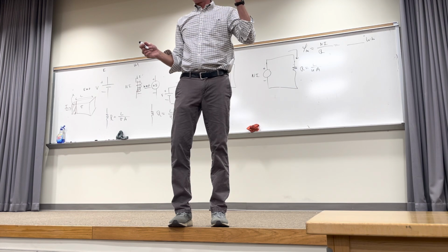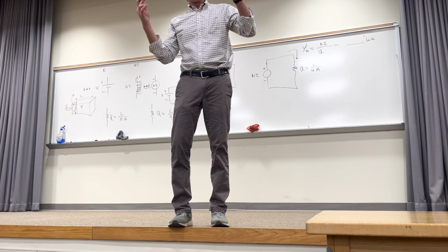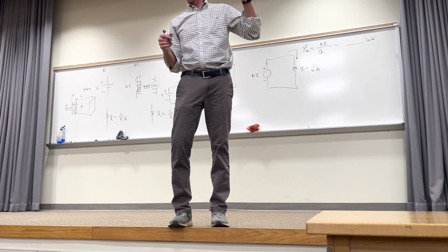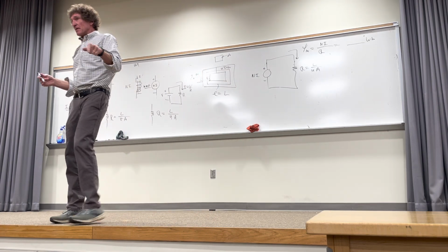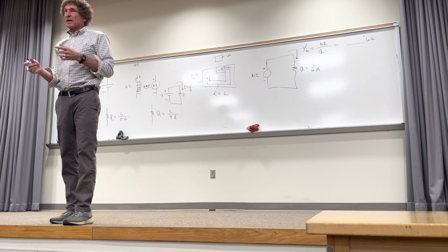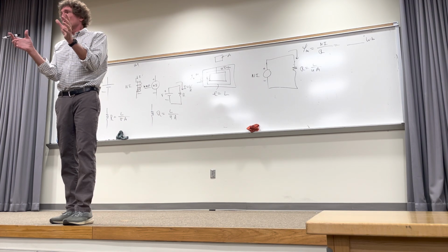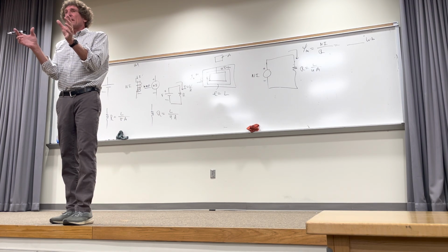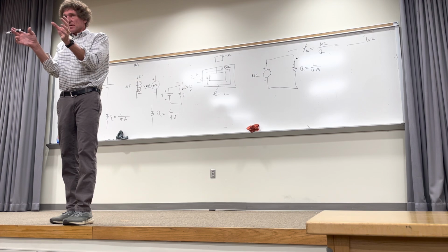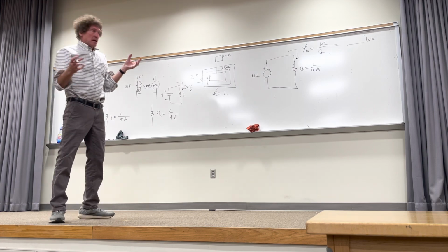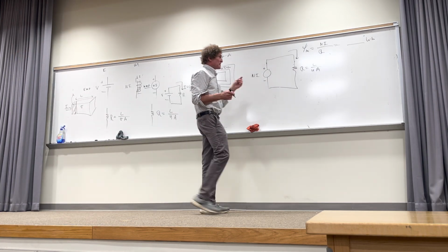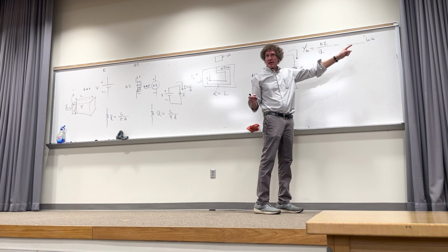All right, so we've covered the magnetic voltage, if you will, the MMF, it's Ni. We've talked about the reluctance of any kind of closed magnetic path. By the way, the reason they use iron core for transformers is that all the magnetic flux basically is contained within it, because it's a low magnetic resistance path. All right, that's the reason they do. Now we get down to this point. This is in Webers, right?